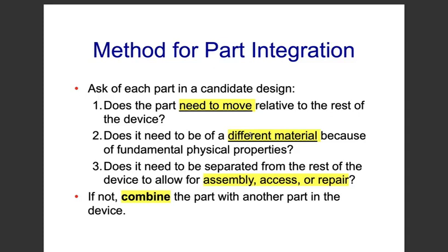Number three is, does it need to be separated from the rest of the device to allow for assembly, access, and repairing or not? If yes, then again, guys, you need more time. But if not, then you can save time. So if not, then combine the part with another part of the device. This is the key point.